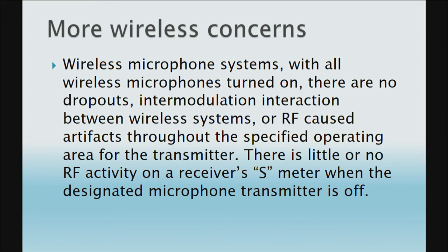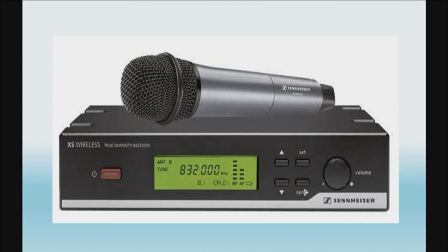More wireless concerns. This, again, is a call out. It's wordy, but a call out from the standard. And by S meter, they're talking about the signal meter. A really good idea, and catching this at staging time. If any of you aren't familiar with it, over here we've got our RF meter. So with that off in the rack, if you look in there and it's peaking up, you know, two-thirds of the way with RF noise, we've got an issue. I'd rather find that out at staging in the shop and say, hey, let's relocate that receiver or put the antenna somewhere else, because a typical problem in one of our new buildings is, I'm not using the microphone, but the system just keeps bursting out this noise into the speakers.